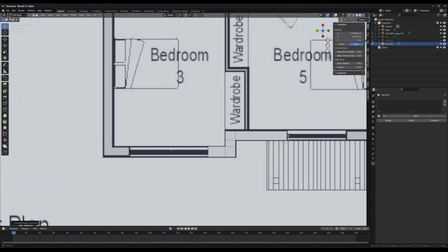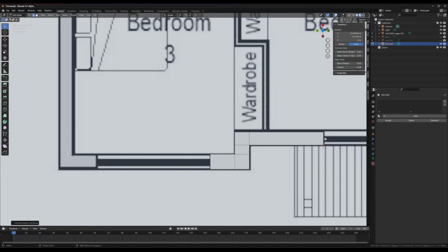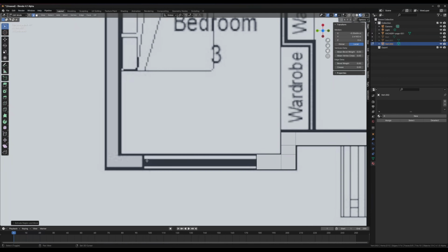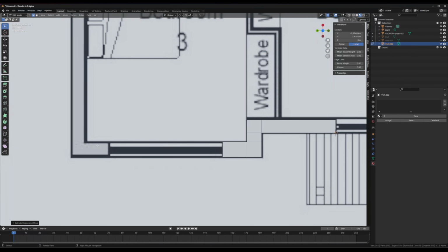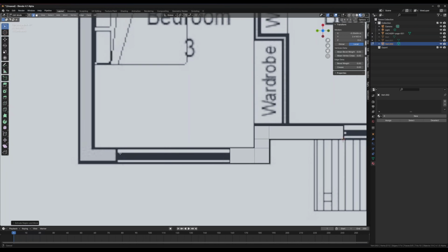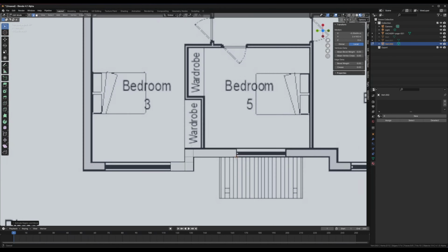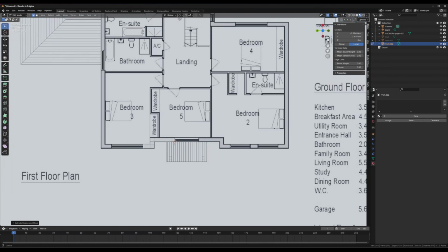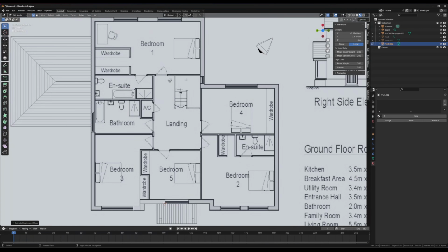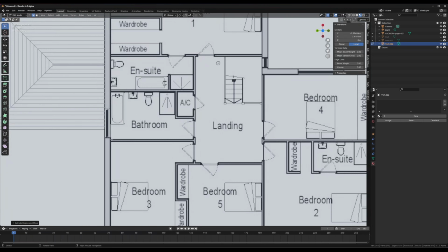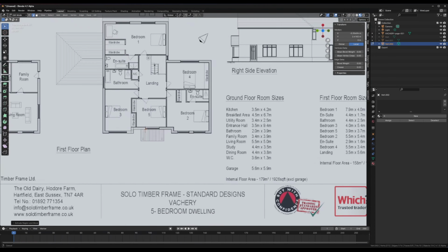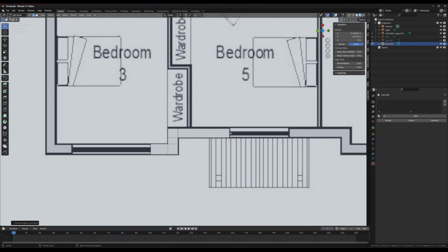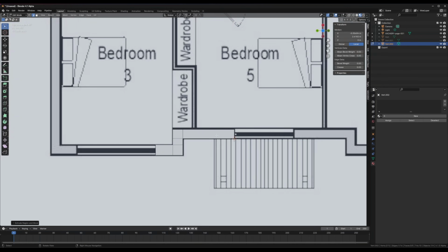And then for the windows and the doors and the entrances, you're just going to leave them completely empty for now. Completely empty. So let's say here, we want to do the same here, but we want it as a separate mesh, because when we light it inside Unreal Engine, we want all of it in separate pieces so it lights properly. If it's all connected in one big mesh, you're going to have lots of noise and lots of issues in your renders. So this is why all these walls are going to be separate meshes. But for now, it doesn't matter. We can continue modeling and separate them later using some techniques, which I'll show you. For now, we're just going to keep going.